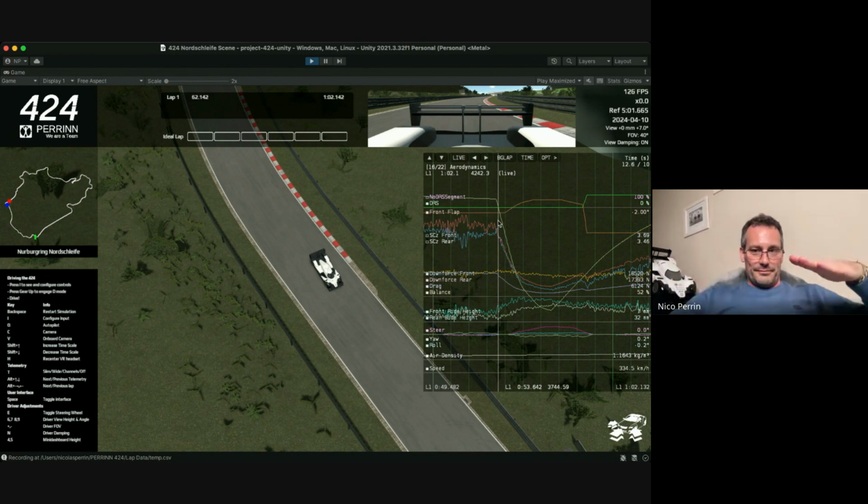The flap is -2 degrees. And as the car slows down, it goes up to 3 degrees. And as you accelerate again, with speed coming up, it drops again. Then we open DRS and it drops a lot. So you see how we make the flap moving.